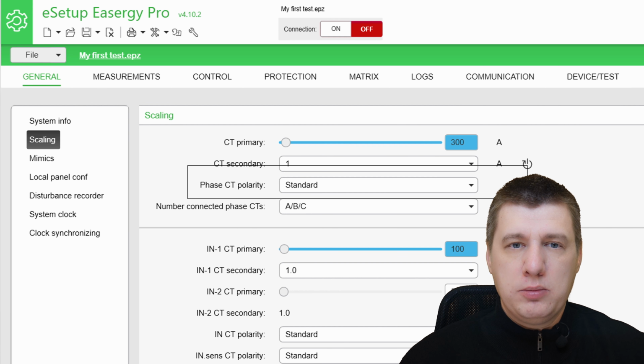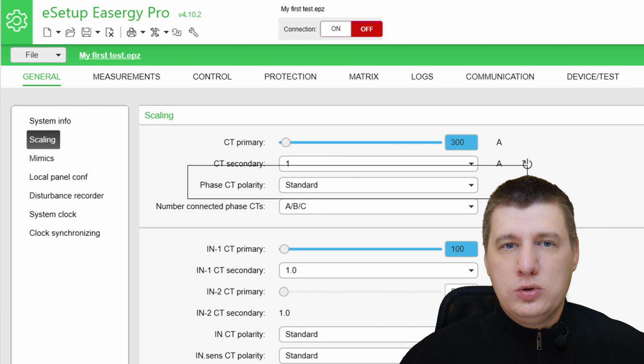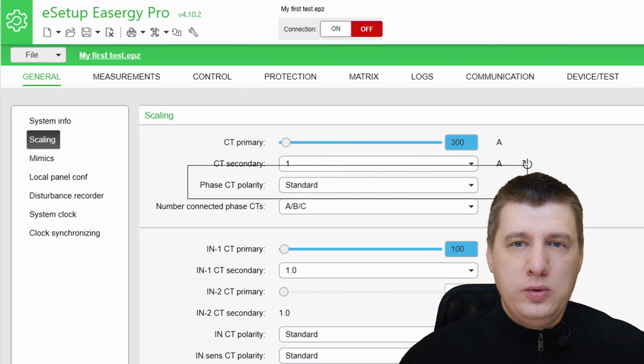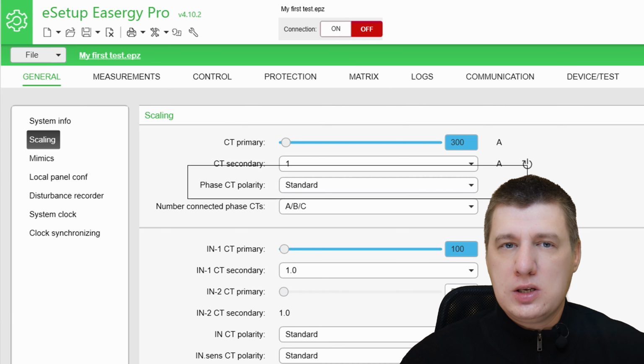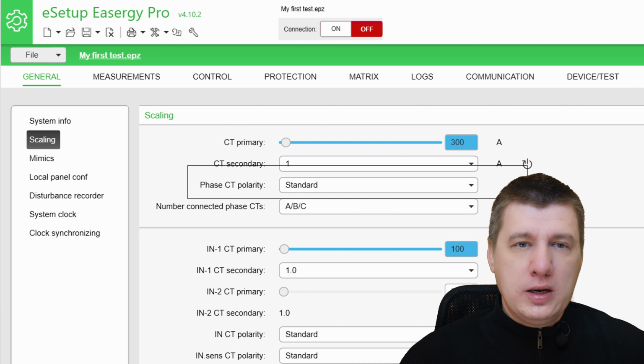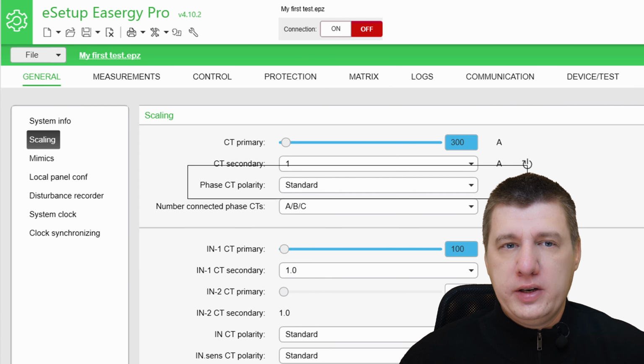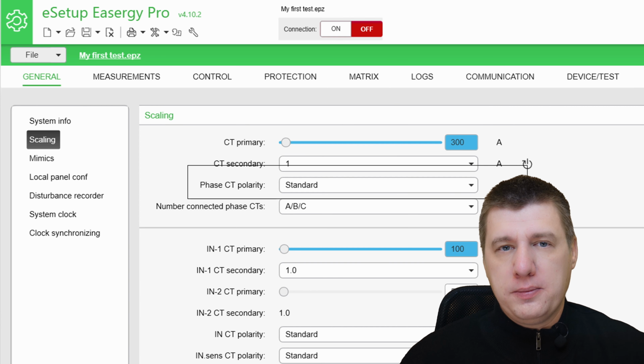Example 2. Incorrect power metering on an outgoing feeder. Current normally flows from the bus bar to the load. If the CT is wired with reverse polarity, the relay will calculate negative power. The HMI would show the feeder as generating power back into the substation, which would provide false data to the SCADA system. Because wiring errors are common, it's mandatory to verify polarity during commissioning.